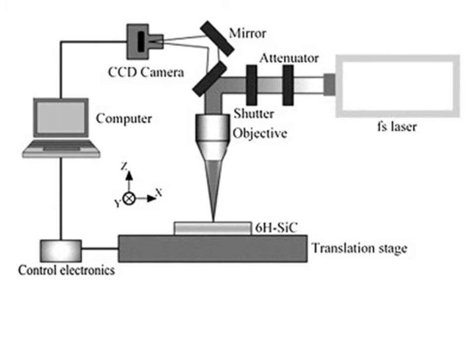So instead of just turning off the whole laser, what we do is we'll keep a shutter in front of the laser. So whenever we don't want the light beam, for example in the case of welding, you have to melt the material and then you'll have to remove the laser beam, and at that point we don't turn off the laser, but instead we will keep this shutter closed. This shutter can be opened or closed depending on our requirement, and then the beam passes through a mirror.